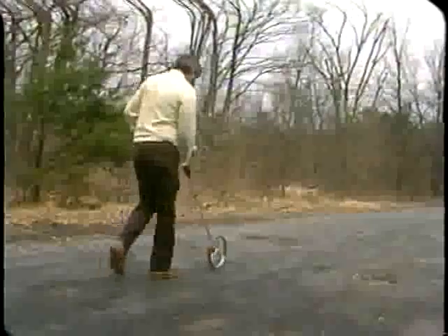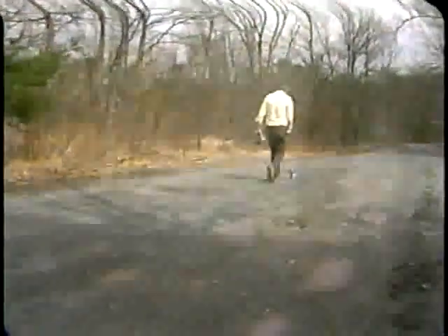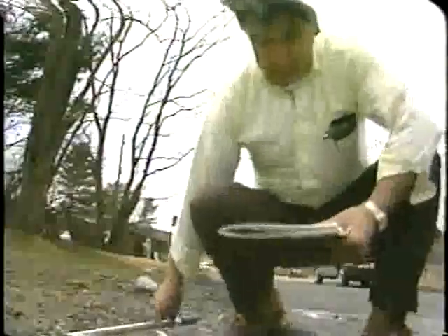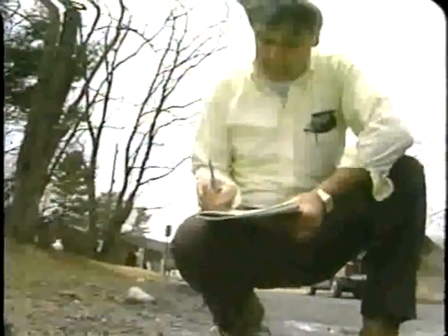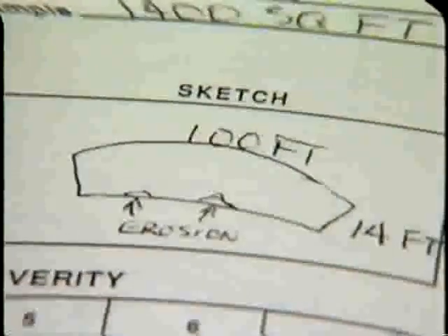Let's look at the proper measurement procedure for each of these. Start by filling out the information at the top of the inspection sheet. You'll find the branch, section, and sample unit information on a map that's already been prepared. Be sure to fill in your name and the date. Then start by measuring the area of the sample unit. That's the length times the width from one shoulder break to the other. Make an overhead sketch of the unit showing areas of problems and road features such as culverts.